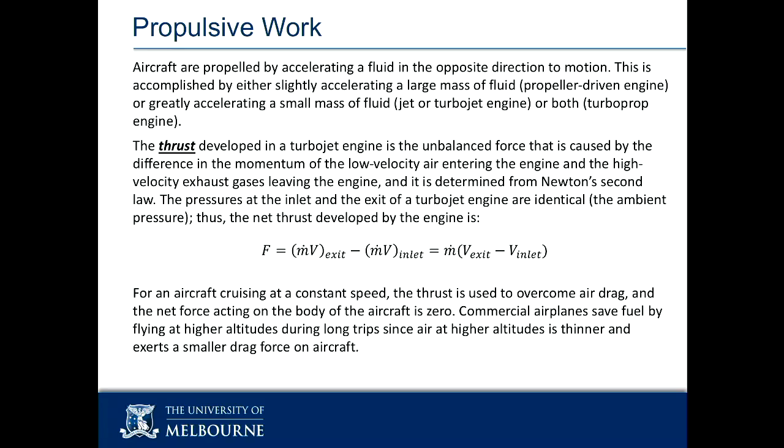It's one of the things that makes going up to very, very high altitudes much more efficient. The other thing that makes going up to high altitudes more efficient is the air that's coming into the system is cold. So it might be minus 50, minus 60 degrees as opposed to 30 degrees or 20 degrees. That difference makes a big difference in the overall efficiency. So getting up high in the atmosphere for a gas turbine propulsion system is actually very good for efficiency.